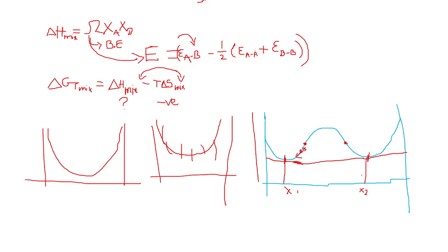Now, there is a formation of twins, and because of the formation of twins, that's how we accommodate the strain inside during the transformation, right? From FCC, or gamma FCC, to BCT, body centered tetragonal.